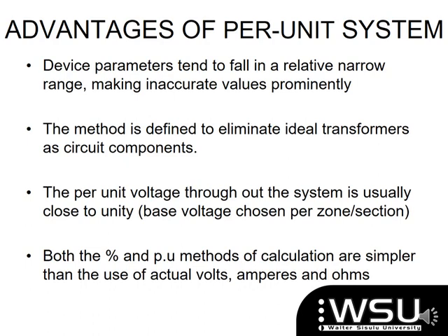So therefore, it would be close to unity, but not exactly at unity. Why? Because your generator is not exactly at the transformer voltage. Although you are still going to utilize that 11 kV as your base, because that's the side of the transformer you are at, it means you are not going to have a unity situation because your generator is not exactly at 11 kV. But where the generator is actually 11 kV as well, then you have a unity system.